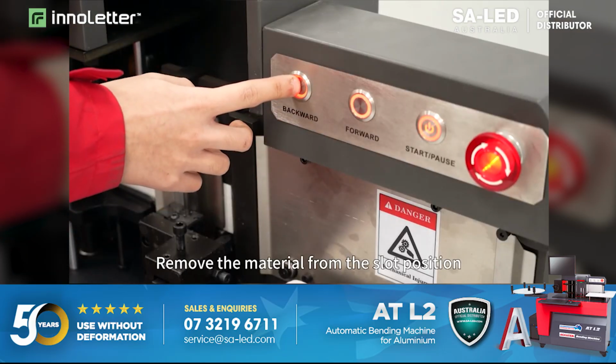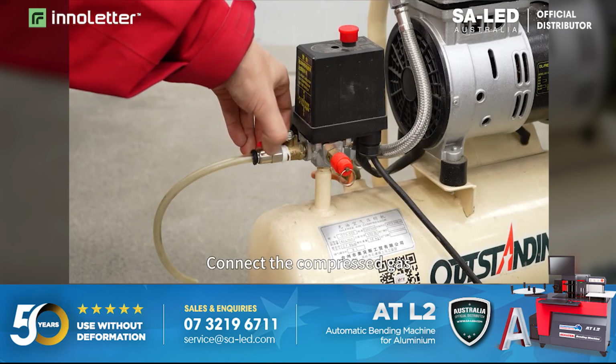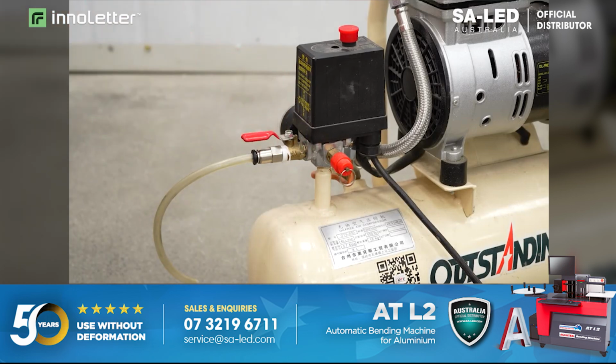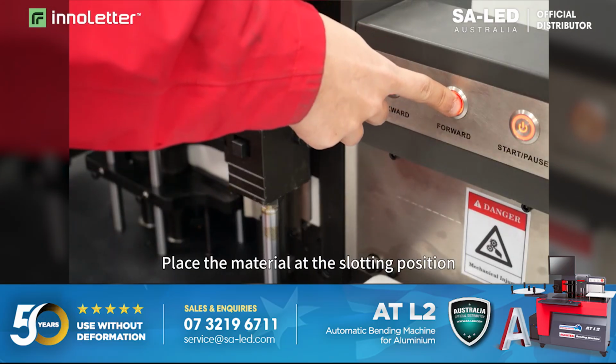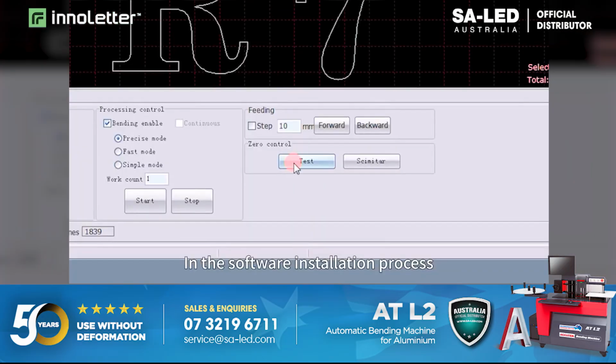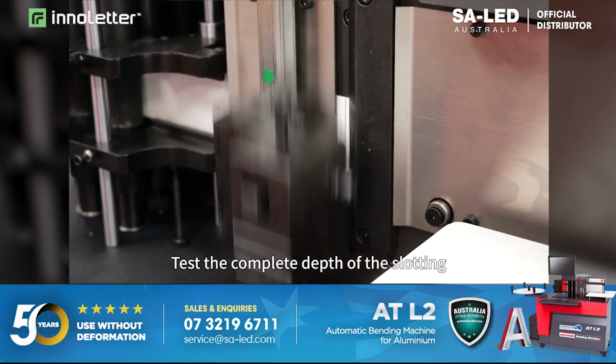Remove the material from the slot position. Connect the compressed gas. Place the material at the slotting position. In the software installation process, click on Slotting Test tool. Test the complete depth of the slotting.